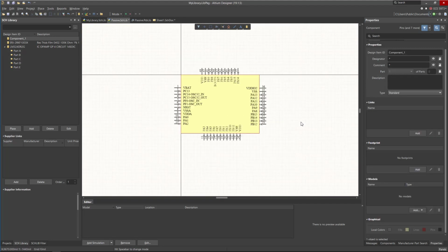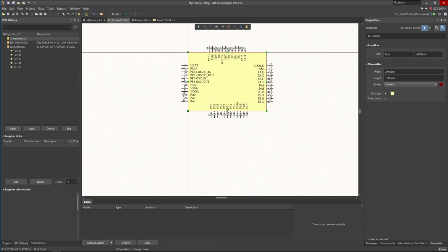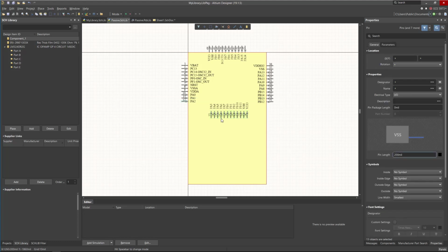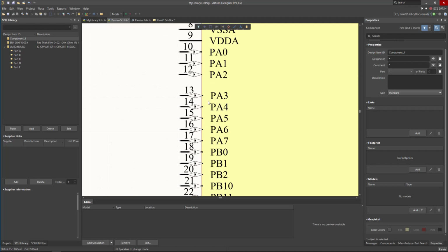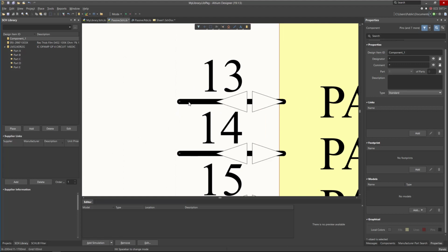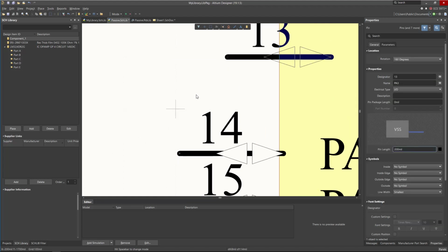Now this is a component. We built the component like that. Of course, you can change how you build the component. Sometimes you might want to have the pins on 2 sides of that component. You can basically move them in here and make sure that your grid is 100 mil. Because you moved the pins when the grid was not set to 100, look what happens now. This is the grid and the pin is off grid, so you need to move it one by one.